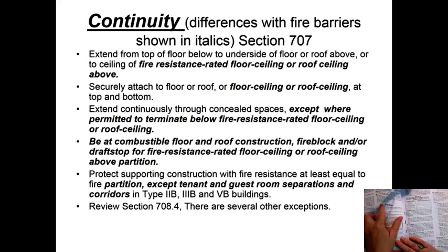When it talks about it in here, you need to read this whole section, because a lot of times it says the fire resistant rating of the fire barrier shall comply with this section. Shaft enclosures: the fire resistant rating of the fire barrier separating building areas from a shaft. A shaft, of course, is a vertical area like a laundry chute, or a mail slot, or an elevator shaft, has to comply with